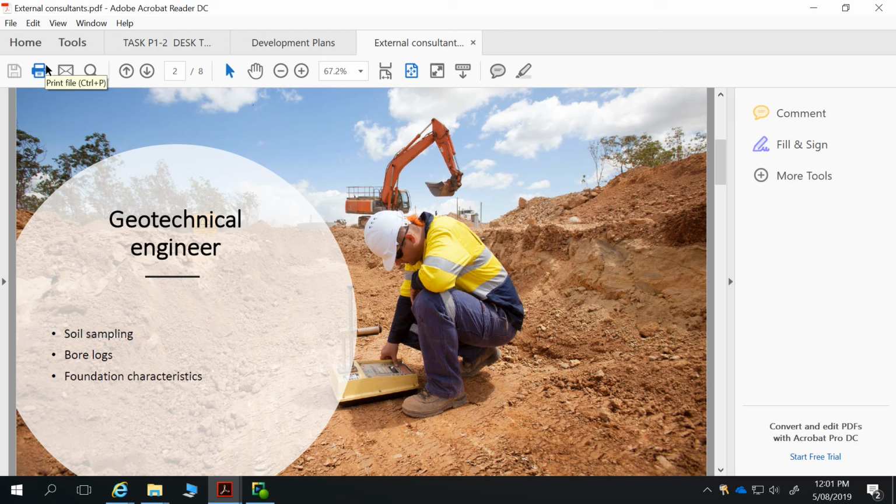But if we've got reactive clays over top of a solid base, sometimes for some building options it's worth going all the way through that reactive clay with our footings, locking into that solid base and elevating our floor up above the ground. Then the soil can do whatever it wants, going up and down, and our isolated pier footings are sitting locked into what's underneath. So sometimes the geotechnical engineer is going to want to know what's down underneath there.